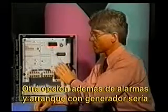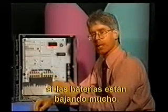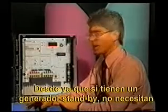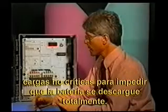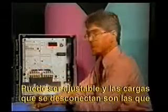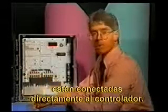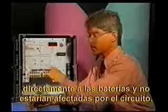Instead of just looking at alarms and generator starting, we may actually want to consider disconnecting some non-essential loads if the batteries are getting too low. Certainly you don't have to do that if you have a standby generator. But if you don't, you may have some non-critical loads, some lights or fans and so on, that you can actually disconnect to protect your battery from being further discharged. In that case, this device has a load disconnect option built in. Again, it might be adjustable, and the loads that are connected directly to the controller would be the ones that are disconnected. If you had essential loads, those would be connected directly to your battery and would be unaffected by the circuitry.